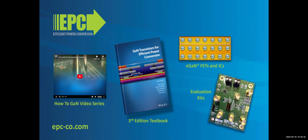So I would say that in my experience, it's quite common and typical to use 5 volt per nanosecond switching in the motors, okay? So the question here is asking for 0.5 volt per nanosecond, which is, I will say, really, really extremely low. The reason to go so low is usually due to EMI constraint in some specific application.